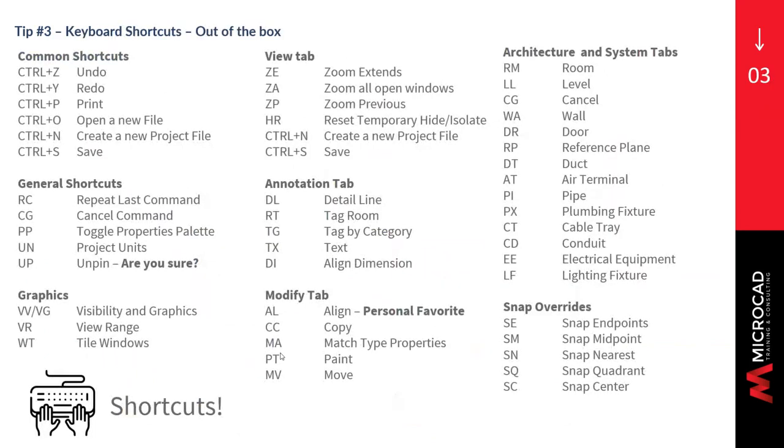Another thing I want to mention is, well, remember that we have keyboards. A major feature of Revit is that it's mouse driven, and that's what most users think. But the keys that you mostly use in Revit are the Control key, the left Shift key, Tab, and Escape. And let me confess something: I'm one of those chronic Escape key users. I need to use it multiple times after I do a command. Same with the arrow keys and the Delete key. But if you are an old-school Revit user, you will also remember the F1 key, which will bring up some help and some tips.